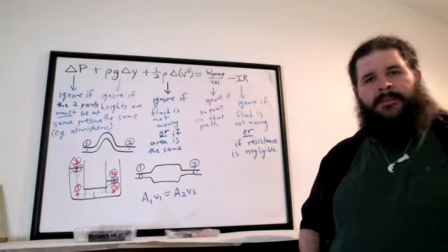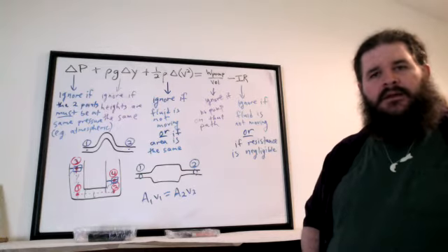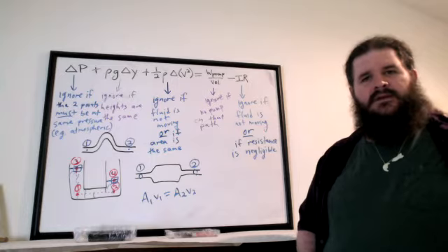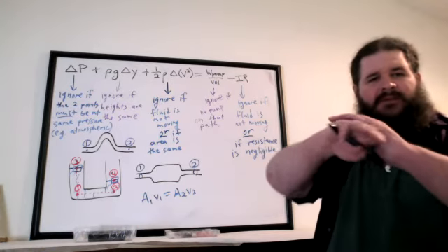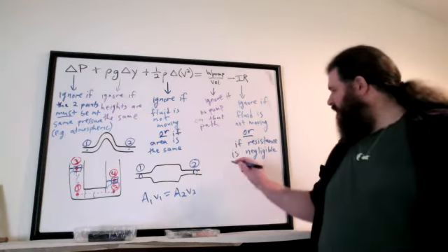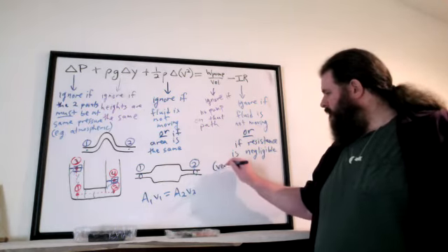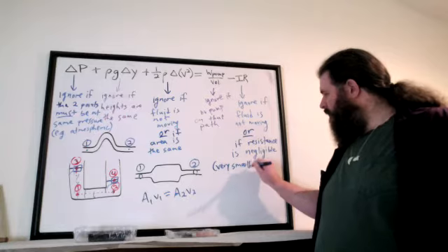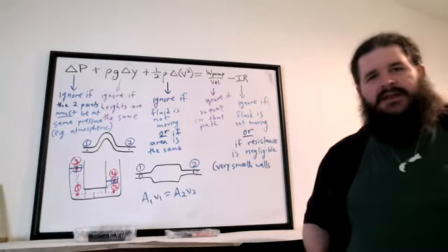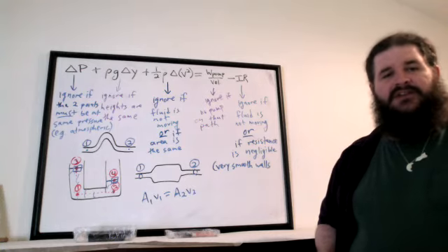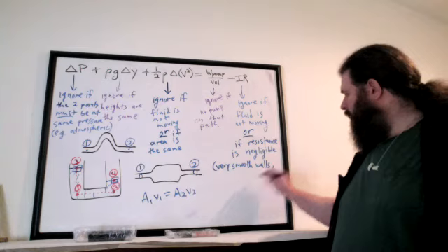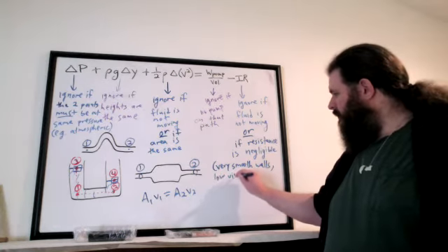You want a pipe that has low friction on the walls, like you wouldn't want something that's rusted. If you can design the walls of the pipe to be very smooth, then that's going to lead to low resistance. Very smooth walls. And also the material of the fluid makes a difference there. The viscosity, really, like how thick the fluid is. So a low viscosity fluid.